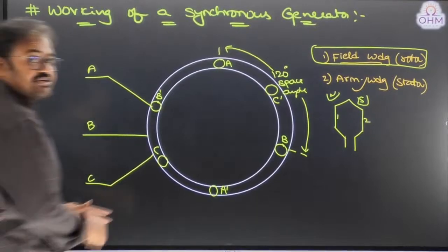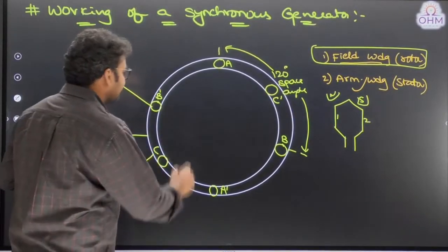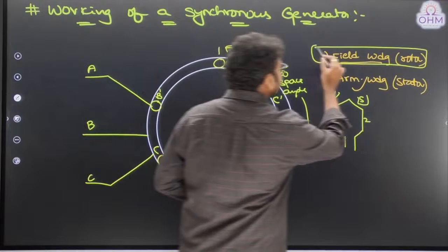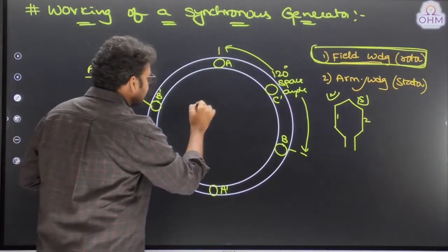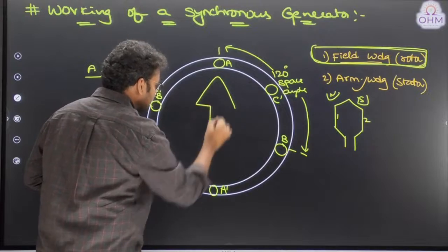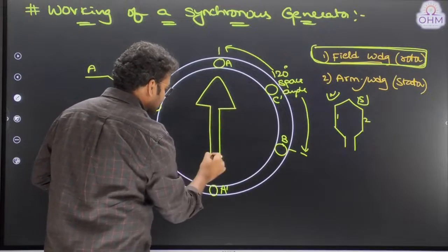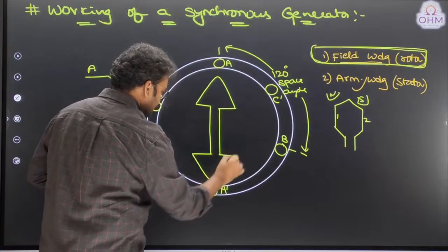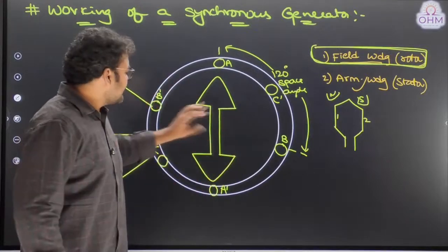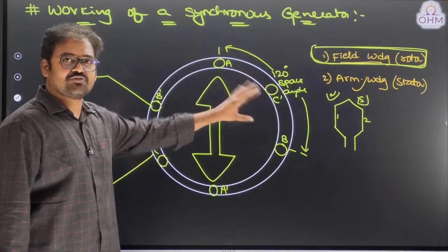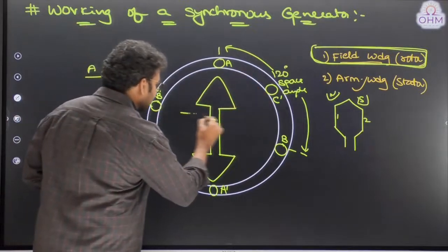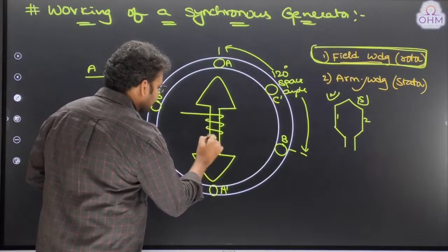All right. Now let us consider the field circuit of the machine. As I told you, the field is on the rotor part of the machine. So let us consider, for example, this is how the rotor is given. A two-pole rotor I am considering. We specifically call this rotor a salient pole rotor, and there are two types, salient pole and cylindrical rotor, which we will see. And this rotor will have a winding, which we call the field winding.